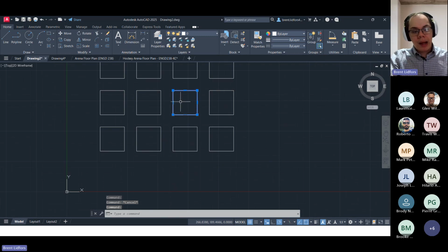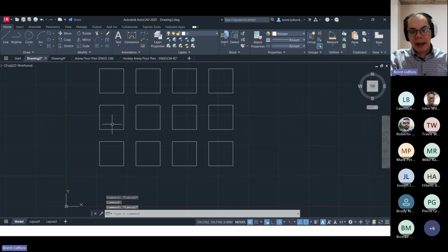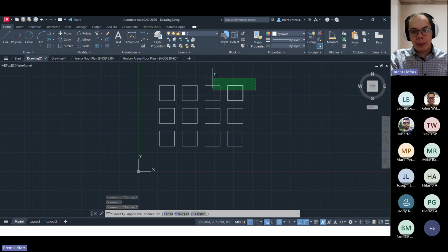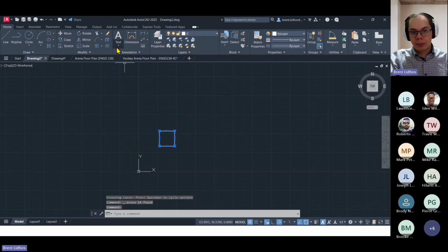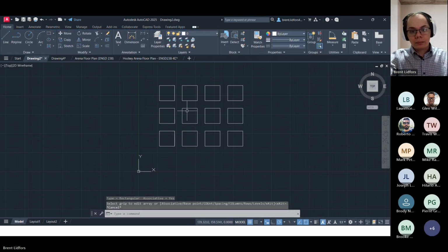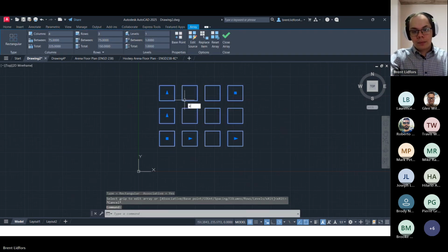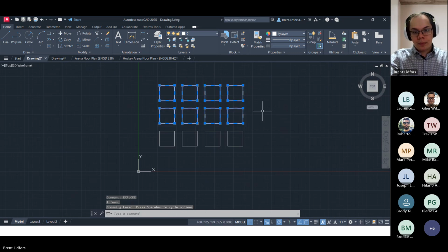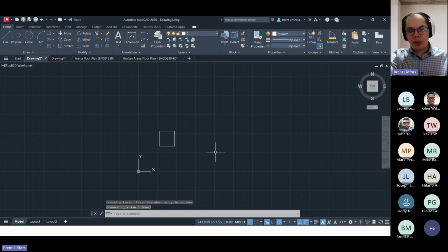Okay. It's a little trickier if you're trying to make this back into an array. You kind of have to just get rid of everything else and then start again. So you can explode to break from an array down to an object, but there isn't really an easy way to get from one object to an array. So that's kind of a re-review of rectangular arrays.